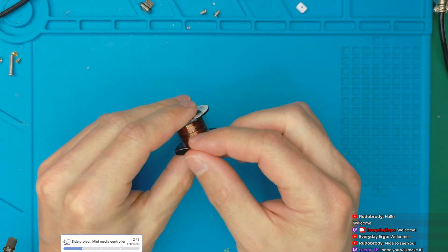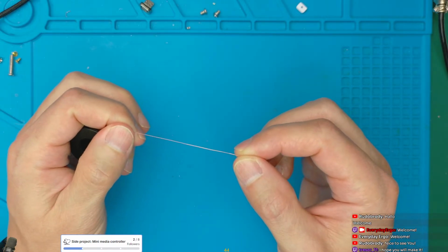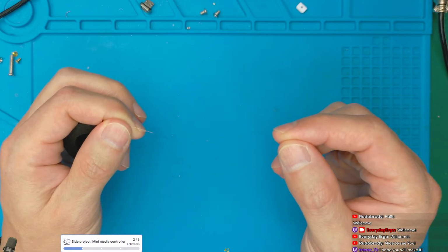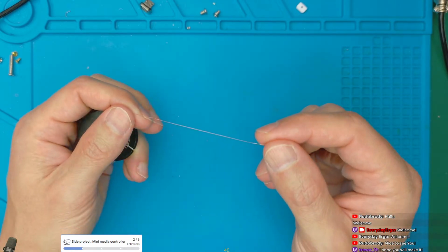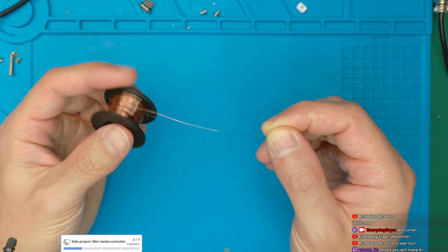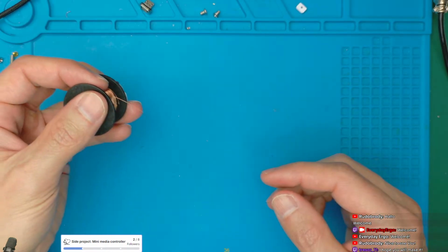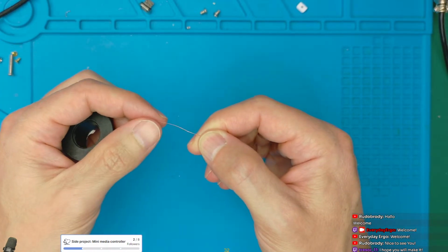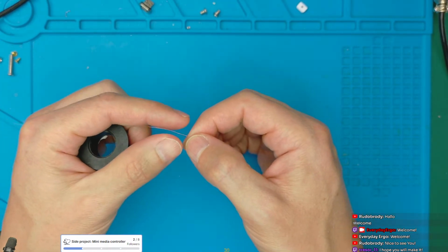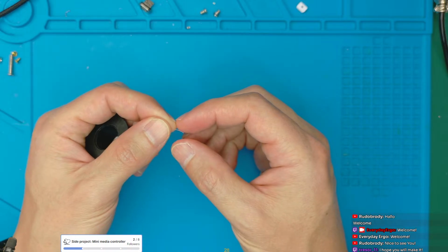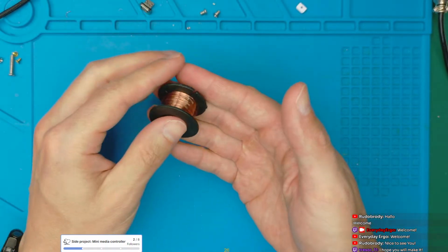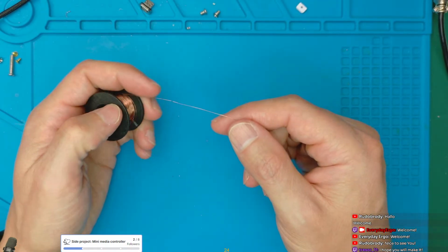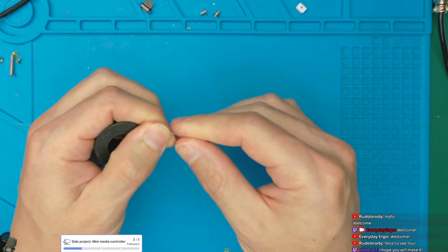This one is super easy to use because it's quite small, very thin. It's isolated, and it's very easy to melt the isolation. So once you're soldering, it will quickly melt, but it won't affect the whole wire. So it's very easy to solder to a point. But the issue is that it's kind of too tiny.